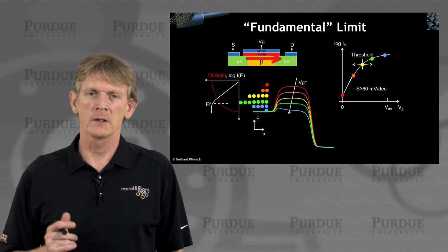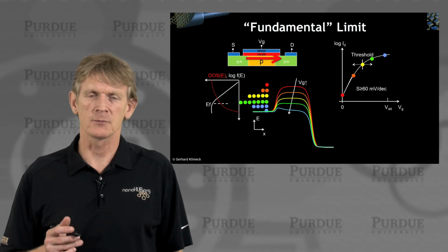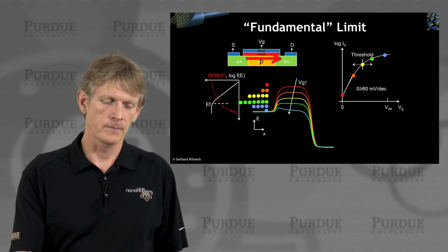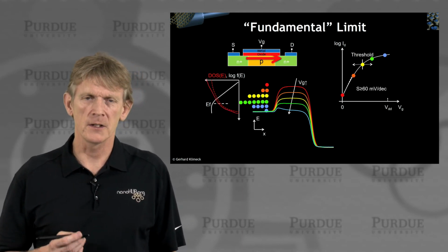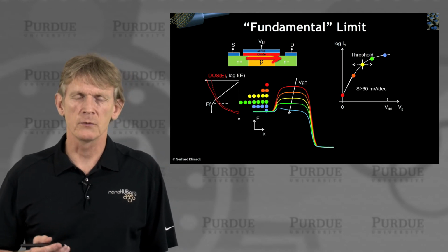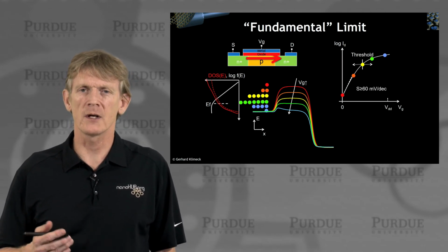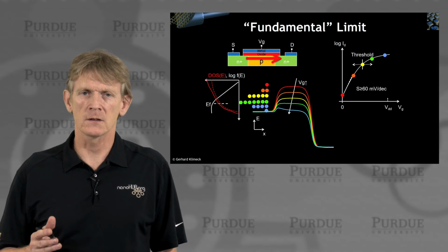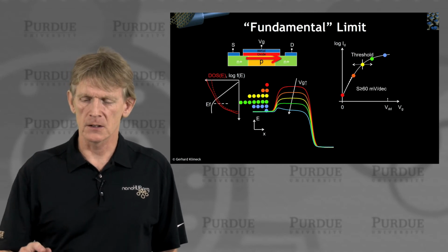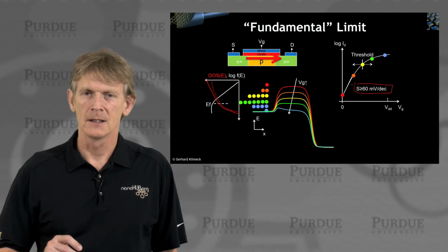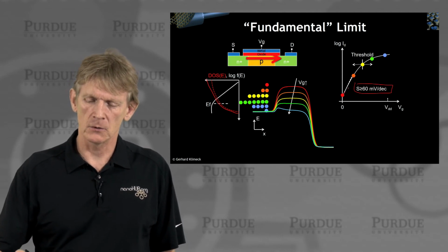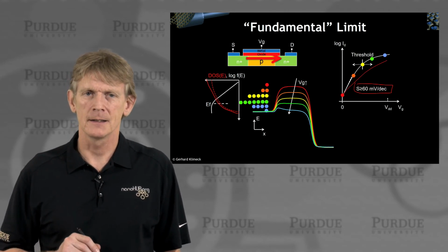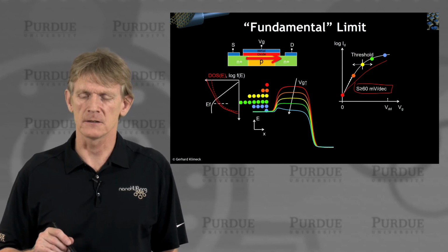And remember, I talked about Fermi function decaying exponentially, linearly on a log scale, a density of states that goes, in a 3D system, as a square root. We've calculated these things now. Now this should look rather familiar to you, okay? So, now we also talked about that this slope here is actually a very critical one, the 60 millivolt per decade. In reality, most transistors don't switch on quite as well, okay? And we'll talk a little bit more about that in the latter part of these sections.